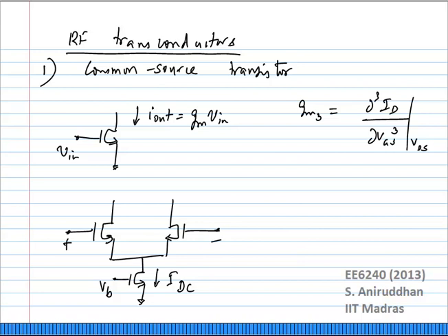How do you improve the linearity of this? Obviously, if you have a common source transistor, let us just go back to this case. Let us consider the common source transistor, which is not purely square law, because most of the short channel MOSFETs you use will not be purely square law. How do you look at the IIP3? You will have to characterize ∂³ID/∂VGS³ for the given VDS.